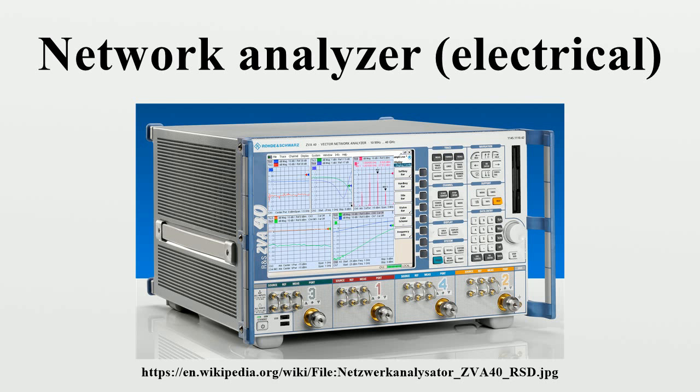Directivity, error resulting from the portion of the source signal that never reaches the DUT. Source match, errors resulting from multiple internal reflections between the source and the DUT. Reflection tracking, error resulting from all frequency dependence of test leads, connections, etc.